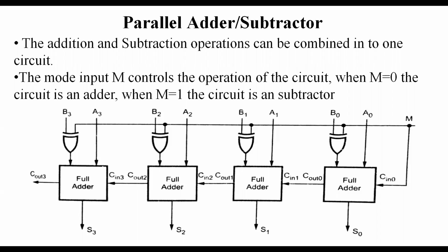It is performing the 4-bit binary addition, and similarly the subtraction operation will be performed by using the 2's complement subtraction. To perform the 2's complement subtraction, we have taken the exclusive OR gate.